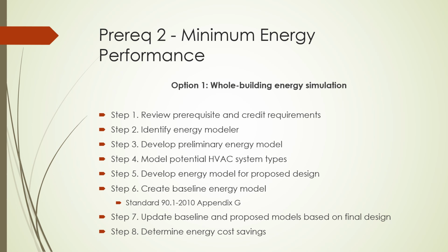As the project progresses and comes into its final stages, both the baseline and preliminary models need to be updated with any final construction details and specifications. And then after this is completed, the final energy cost can be determined. You need to keep in mind that if you have any on-site renewable energy systems, they do not offset energy costs in this prerequisite, but they can later on in the credit.